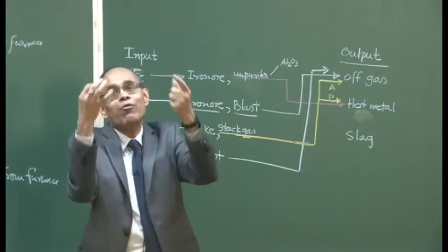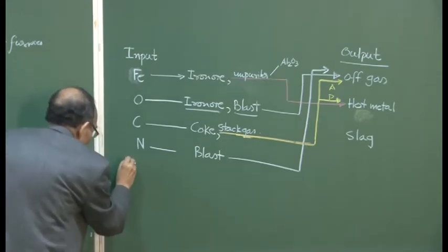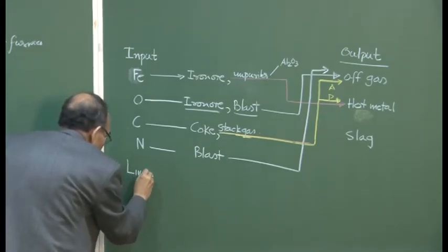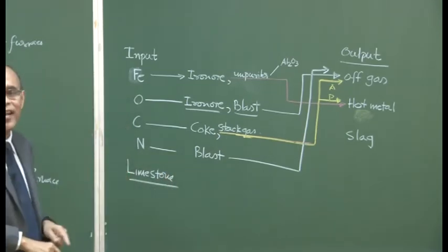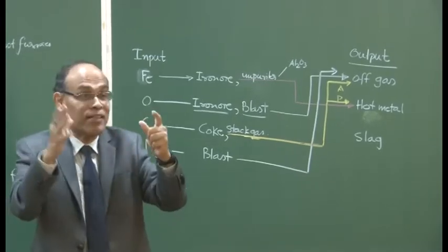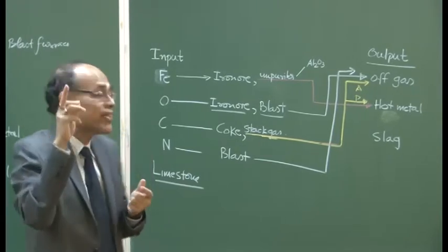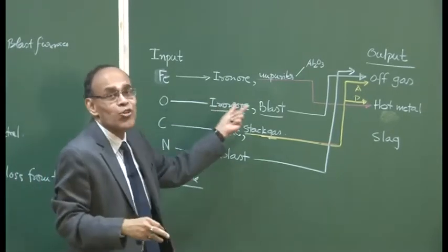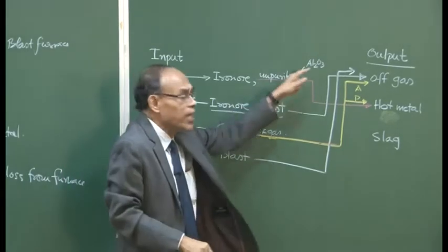It will go to the slag forming temperature and then react with the calcium oxide present in the lime, if you input limestone. Even for lime we need not dissociate it, to say that oxygen is coming in through lime because its formula is CaO. No, because lime does not undergo any reduction or dissociation in the blast furnace, the temperature is not thermodynamically favorable, and so is true with Al2O3.